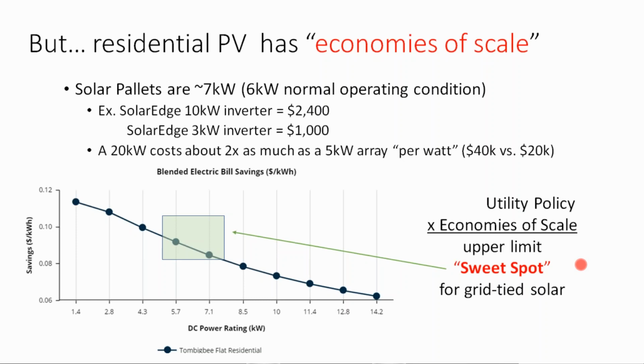But then again, there's that whole outflow rate. Whereas if I do a 5 kilowatt project, it will not produce much outflow onto the grid, whereas a 20 kilowatt would. And so that kind of gets you into a sweet spot where generally in Mississippi, if I'm doing a batteryless array, it's just going to be a 7 kilowatt system. The customer who got a 14 kilowatt was not on a co-op. He was on Entergy, and Entergy has a buyback rate of 7 cents instead of 2.5. And so, that's why we went with a little bit larger of an array for that particular customer.